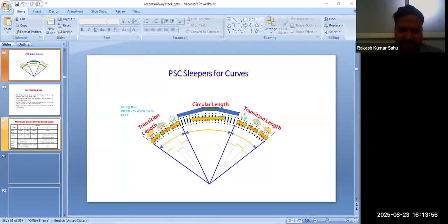The elastic rail clip's main objective is sufficient and continuous toe load on the rail under static and dynamic conditions, to ensure no separation between rail and rubber pad, to ensure minimum uplift under percussion wave, and also provide creep resistance, that is resistance against movement, and always to connect the rail in any loading condition.